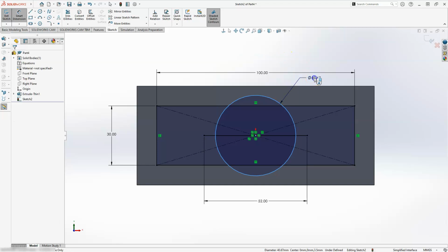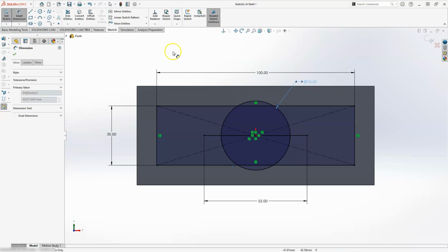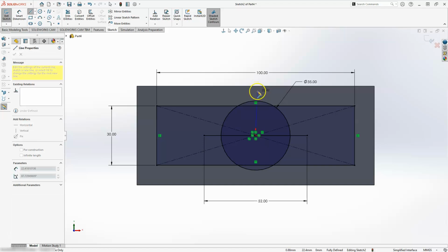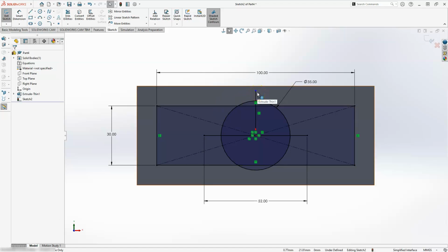And there's another way I can do this. I could have simply drawn a line at whatever the radius is. But if I'm doing it this way, this will allow me to go ahead and place the exact diameter of this circle on here. And then I can draw a line going straight up from that center, going to here. Okay, let's escape out of here. I just want to make sure that this line is touching this. Now the reason I'm doing it this way is if this ever changes, I can just change this one number and it's going to automatically change the position of that.